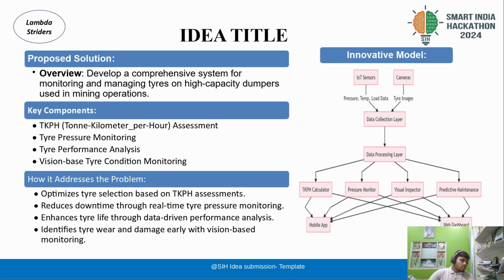Each tire on these dumpers comes with a designated TKPH value. This TKPH value tells us how much load can be covered by this tire over a specific speed.